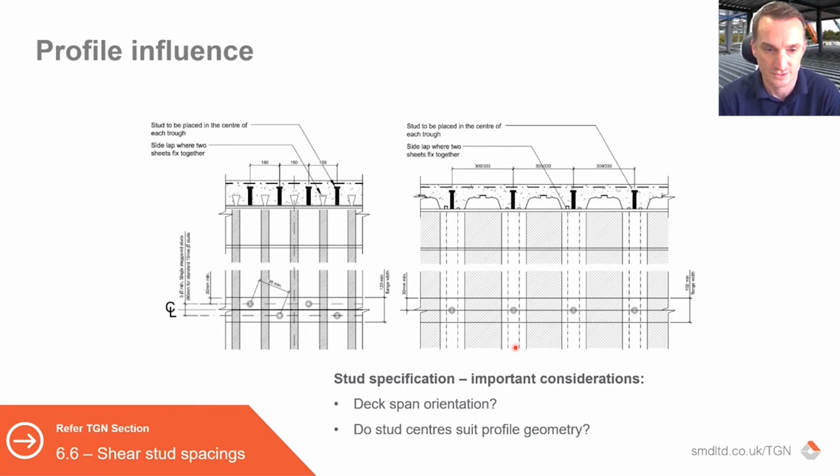The R51 Plus that you've heard me mention already, that is 150 spacings, so 150 trough spacings, so permits a stud at 150 centres across the profile, or pairs, you know, at multiples of 150, but nothing different. And the trapezoidal profiles we offer are TR60 Plus and TR80 Plus, and they permit a 300 or 333 centre. The TR60 Plus has 333 millimetre trough centres.